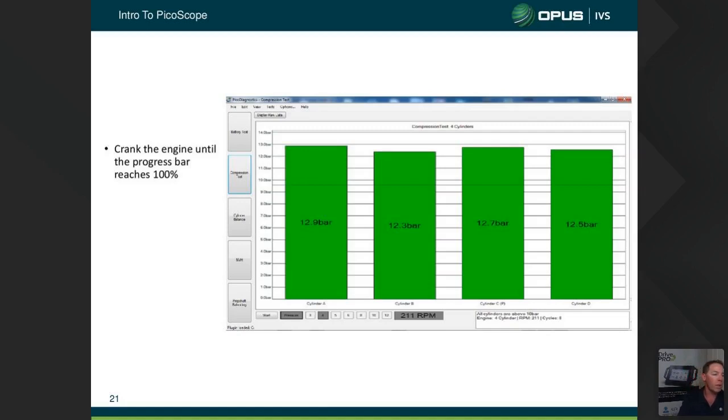I know it sounds a bit weird only checking 1 cylinder to get pressure values on all of them, but I've tried this and I've tried to fool it on 3 or 4 different motors where I've moved it around, I've put it in different locations, I've tightened the valves up on an engine so I actually get one to leak. Not the one I'm testing, and this reads exactly the same. I've put a manual compression gauge in there and got exactly the same reading. So I'm very, very confident this system works very, very well.